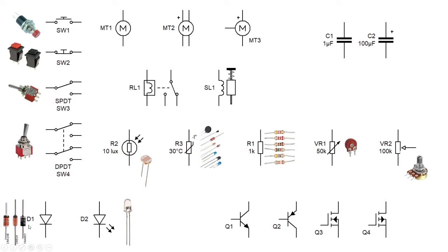Diodes, they're a very important thing to learn about. They're effectively a one-way valve. Now, provided you don't exceed their voltage, they will stop current going in one direction. Now, I've actually put the symbol and the photos the other way around. So this bar here, almost think of it like a no entry sign, a stop sign. Now, the idea is the current cannot go this way. The arrow is another clue like that. So the current goes from positive here down to negative that way, but not the other way around.